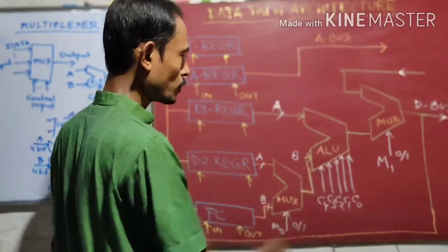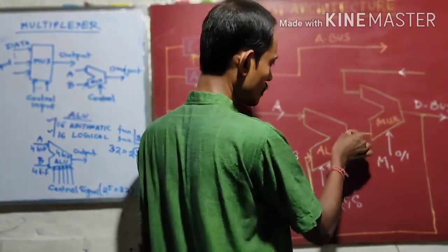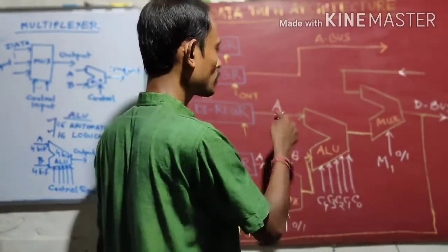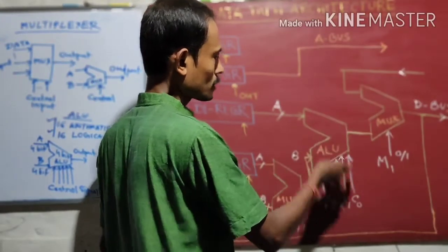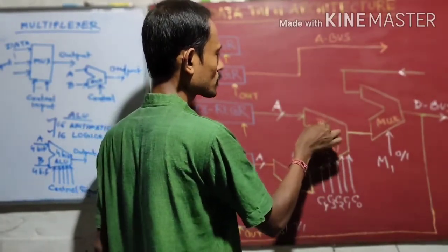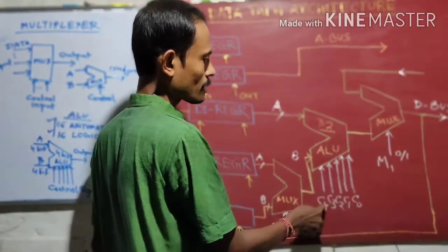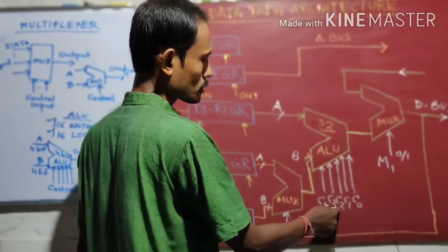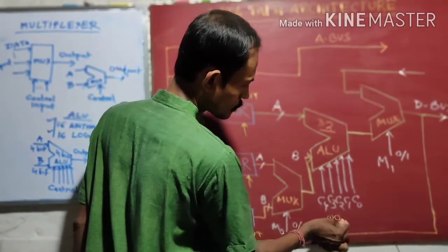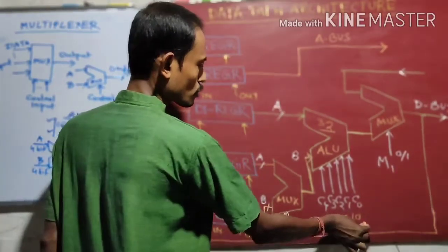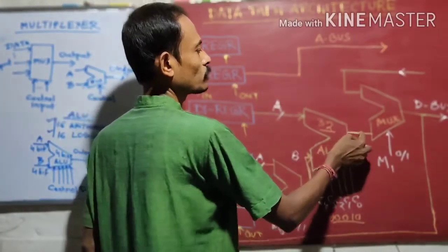into the ALU part. And then from this ALU either any of these inputs can go out as the output, otherwise some operation. So you can consider maybe 32 operations can be done by this ALU. That's why there are 5 control signals, C0, C1, C2, C3, C4. All these are the 5 control signals. Suppose there are control signals 0, 0, 0, 1, 0. On the basis of this control signal, whatever value comes on this B leg will come out as the output.